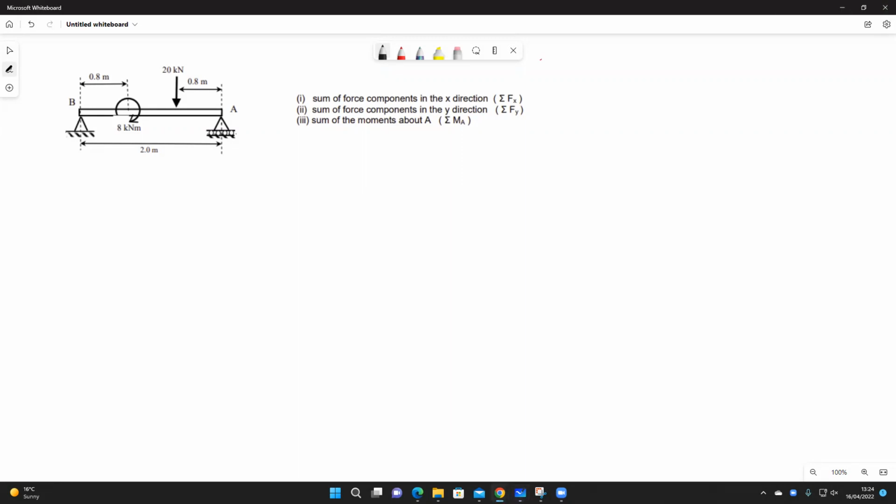The first thing we would do for this particular problem is start by drawing a free body diagram. The purpose of this diagram is to understand the nature of the forces acting upon the structure and how they behave. This is essential for any problem that deals with looking at beams. Often these sort of problems can also get complex, and you could be working with UDLs instead of point loads. So therefore, it's highly recommended that you draw a free body diagram prior to attempting this question.